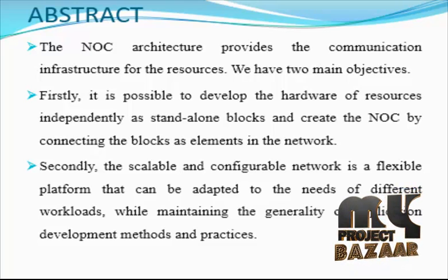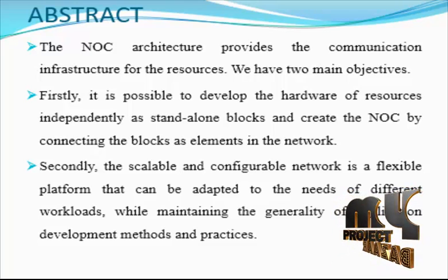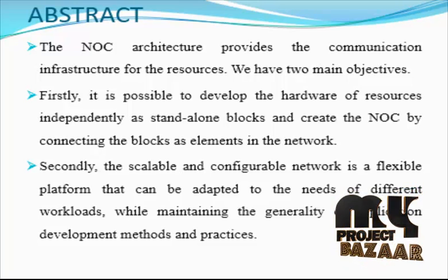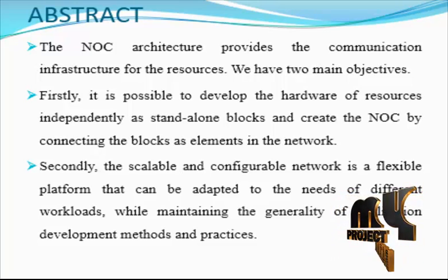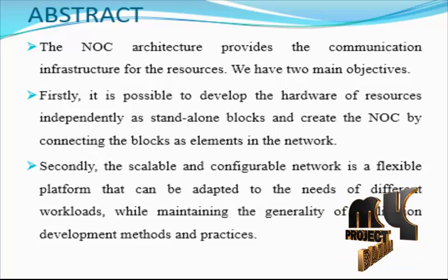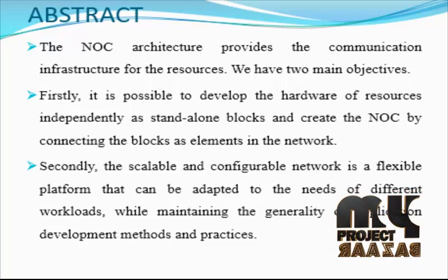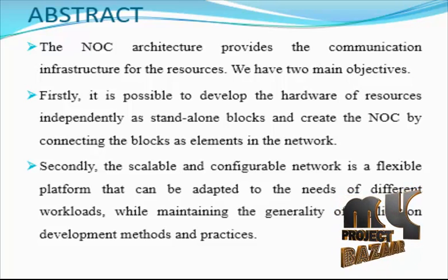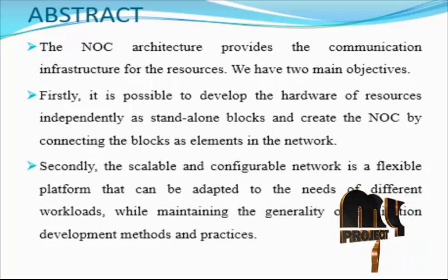The processing elements and the communication network exploit inherent inter-task parallelism, which typically increases as the number of processing elements increases for efficient system performance. However, the key to maximizing the leveraged parallelism in modern and future SOCs is an efficient and scalable inter-processing element network communication methodology.